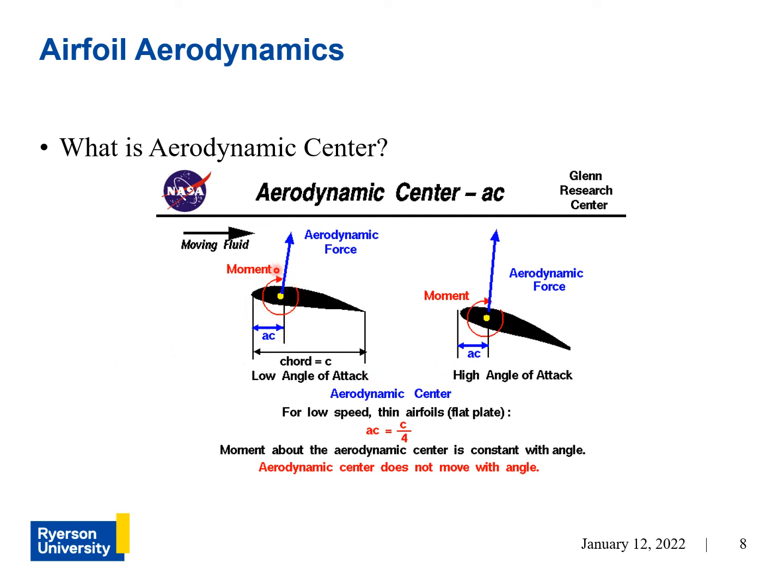Now here, the pitching moment is positive when it's pitching up, and that's why in this diagram it shows as a clockwise direction, because it's pitch up. And this is just for reference, but if you put a flow of air here on this airfoil, the pitching moment would actually be going that way, because this is a positively cambered airfoil.